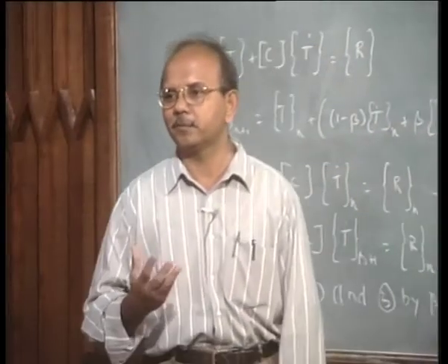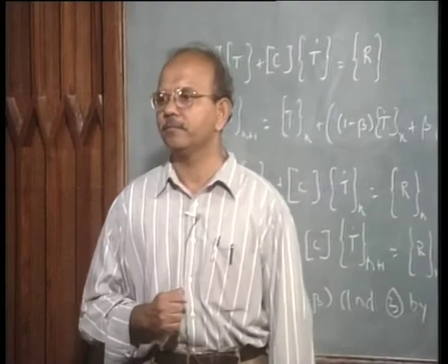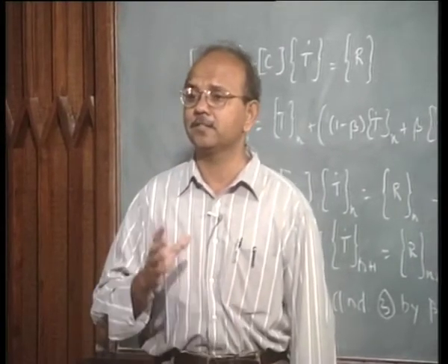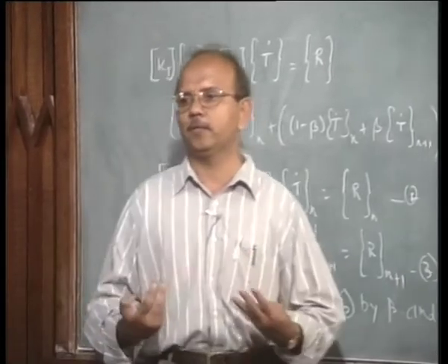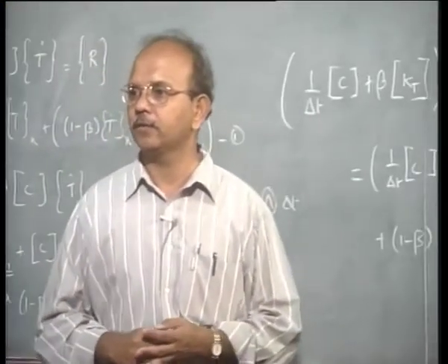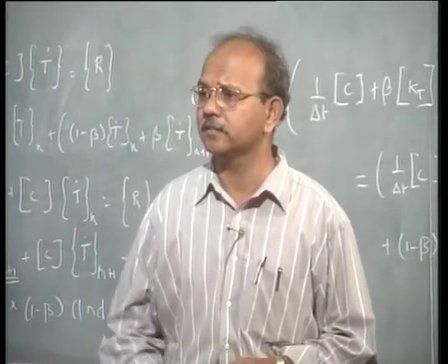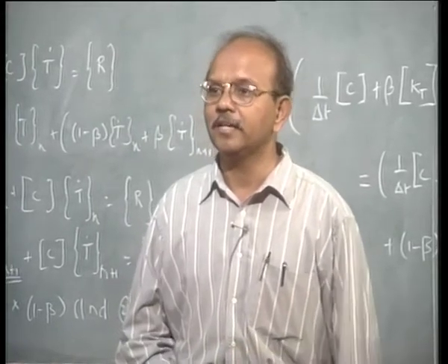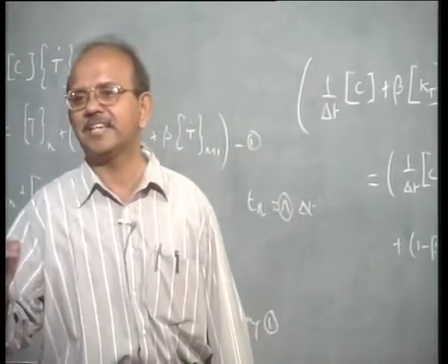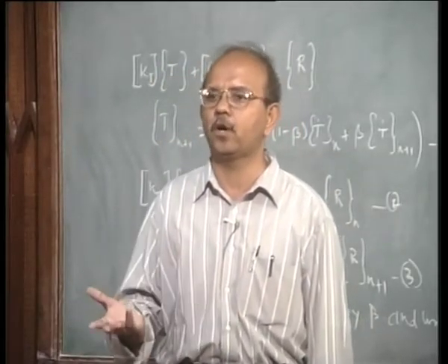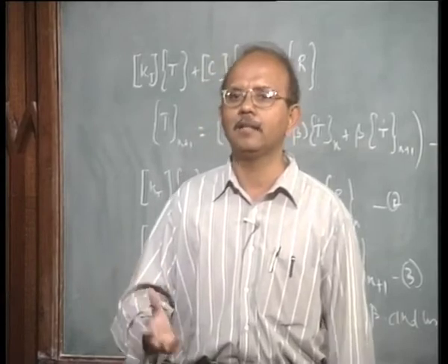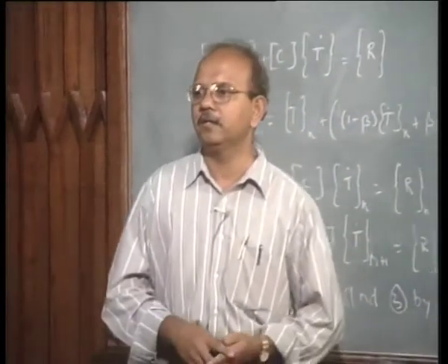This is some sort of a catch-22 situation. I want to emphasize this. What is it? Now I want to use finite element analysis for design. That means my product does not exist. If I can verify whatever results I have, I need not do finite element analysis. I can as well make the component or the product and then test it experimentally and be done with it.